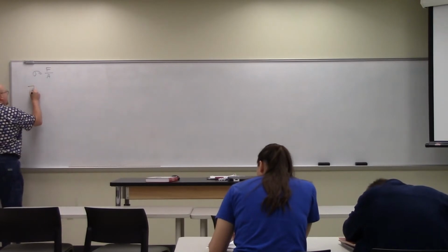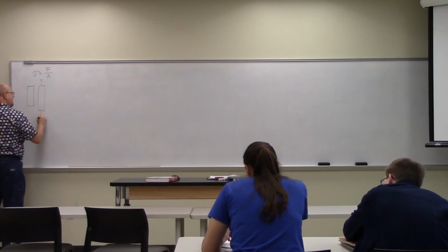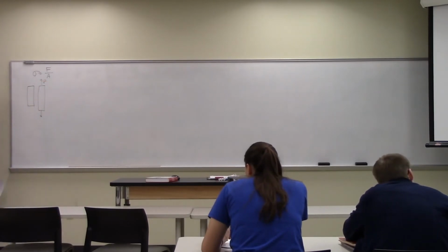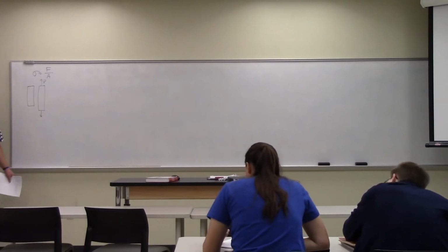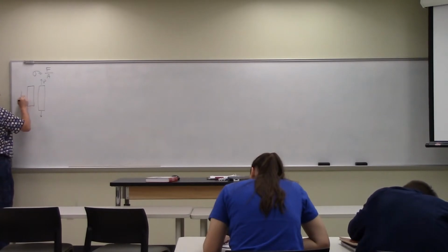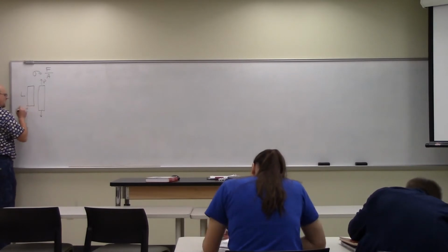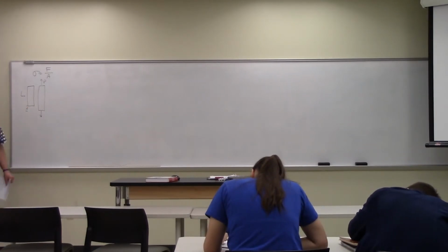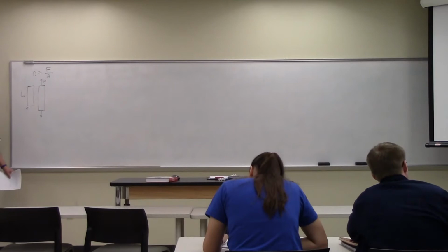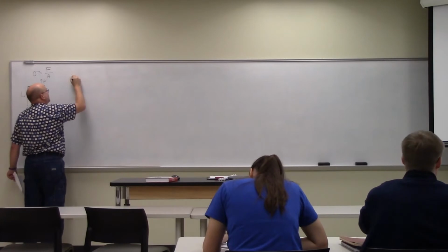So in other words, if I have a component and I apply a load to that component, it will deform. Right? It'll stretch. So if the component starts off with an initial length L naught, there will be some increment of length delta that is the change in length, the extension, that is the deformation. So we want to be able to characterize that deformation, delta.